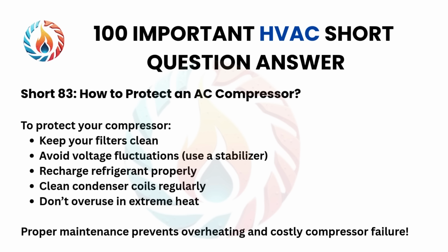Short 83. How to protect an AC compressor? To protect your compressor, keep your filters clean. Avoid voltage fluctuations. Use a stabilizer. Recharge refrigerant properly. Clean condenser coils regularly. Don't overuse in extreme heat. Proper maintenance prevents overheating and costly compressor failure.